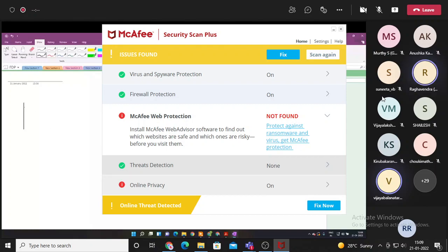Text to bits. We don't do channel encoding over here because at this point we thought that was not necessary. I'll tell you why as well. Post which we directly go to packetization. The reason is that we do not need any modulation. Proper digital modulation schemes are not required because your LED is only capable of 2 states, off and on. So we directly go to packetization. Again, sync.